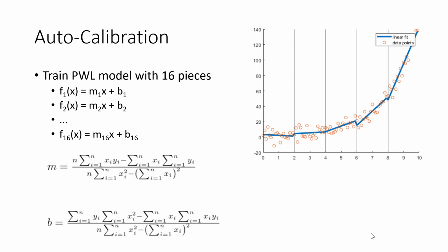You can see that this is actually an exponential function. I added noise to it to create each one of these samples. You look at this and think, oh, that looks like a pretty good non-linear, exponential, but it is linear. It's just divided into linear segments, built up from individual linear segments. That's what we want to do for this lab. In this case, we want to do 16 segments. So we're going to take the voltage from 0 to 14.2 volts, 0 to 3.3 volts, which is what we're reading.